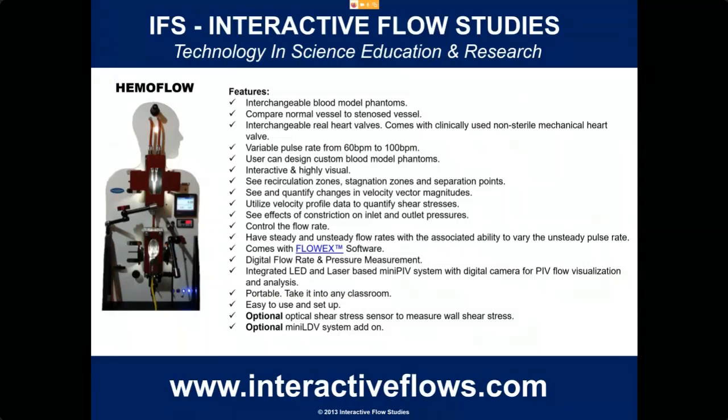It comes with FlowX, of course. It has digital flow rate and pressure measurements. It has an integrated LED and laser-based mini PIV system combined with a digital camera for PIV flow visualization analysis. This is also portable. You can take it into the classroom. Easy to set up, easy to use. Optional optical shear stress sensor to measure wall shear stress. An optional mini LDV system also to add on.